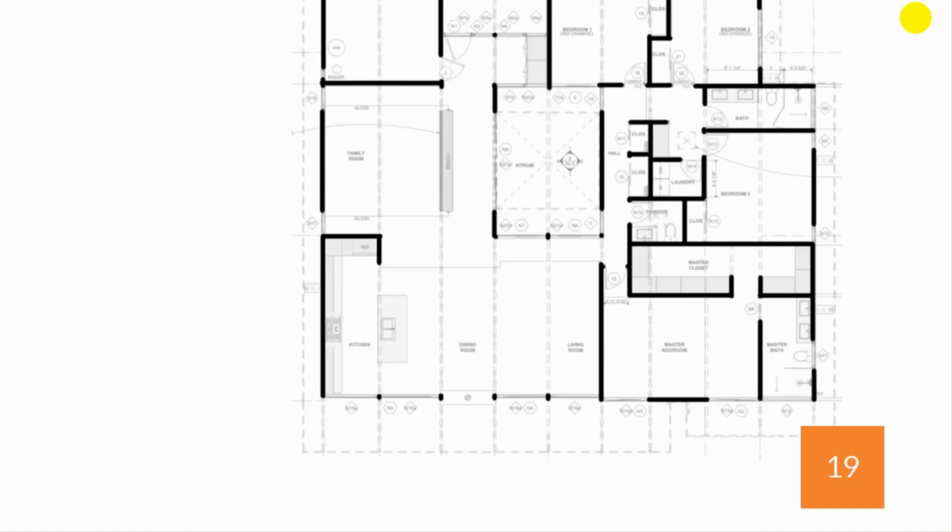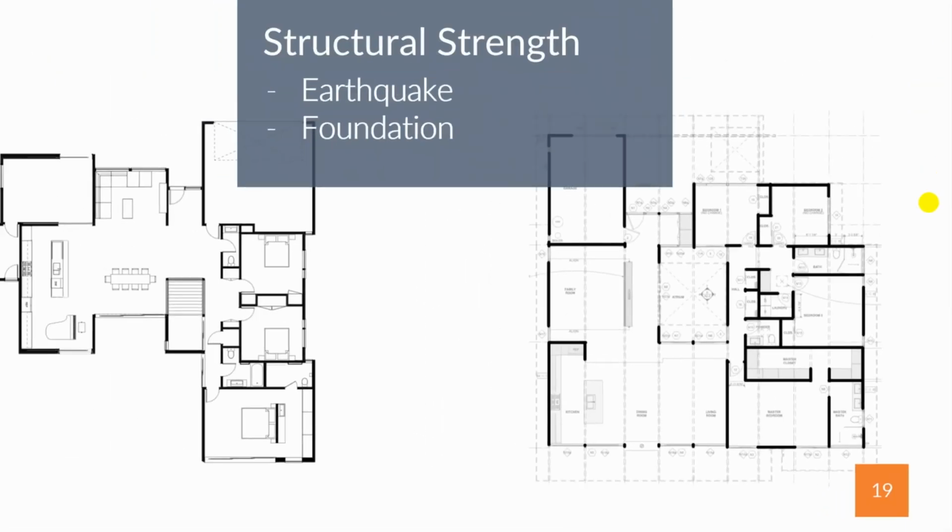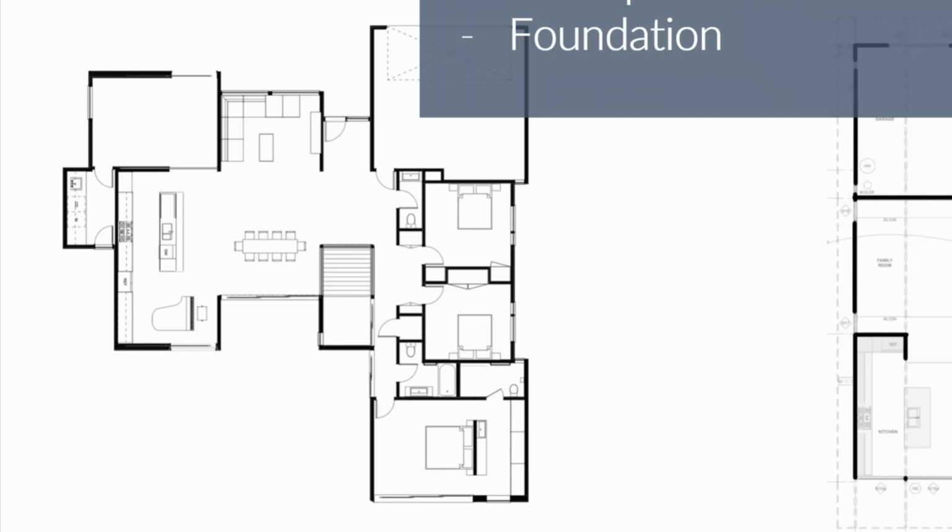And since we're doing that, it's a moment frame. This house has more solid walls in every direction that are artfully placed and can be shear walls, but still allow a feeling of openness. We use them a lot for pocket doors, so the exterior doors and the interior doors can pocket into some of those shear walls and disappear. So it's a nice feature.